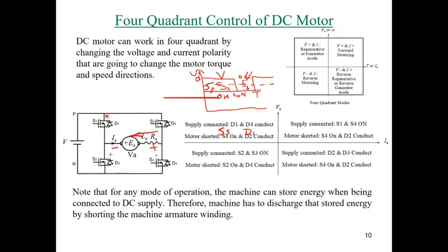No place to move here because the diodes here will not conduct in this direction. Is it right? So we have only that direction. So it will force D4 to turn on in order to dissipate its energy. Okay? And in that way, we can control the machine voltage. So this is the way of speed control. Is it clear? Yes. Okay. Right.